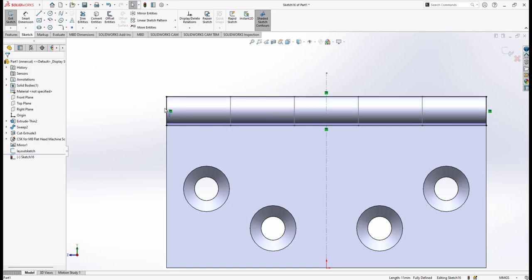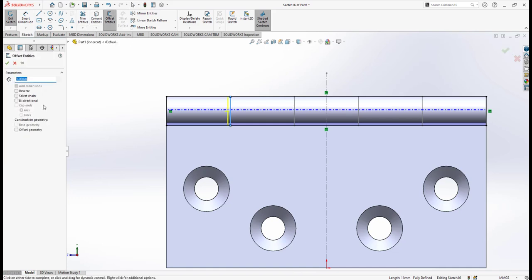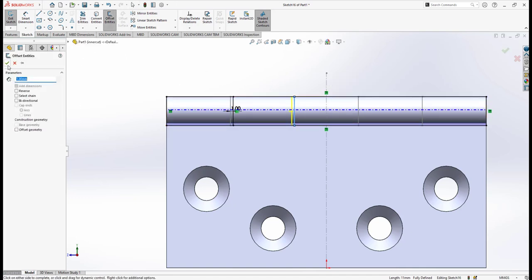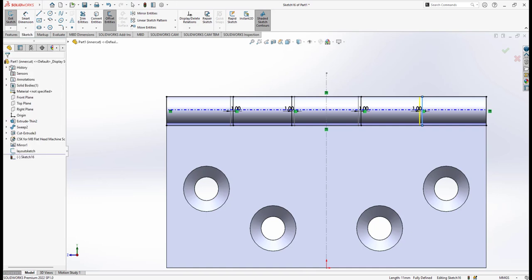The next step is to offset the parting line so that we can specify the locations of the material that we want to cut. So for the outer cut configuration, I will be shifting this line by 1 millimeter inside. I will be reversing its direction. Similarly, offsetting this by 1 millimeter, this by 1 millimeter in the other direction, and finally this line by 1 millimeter.